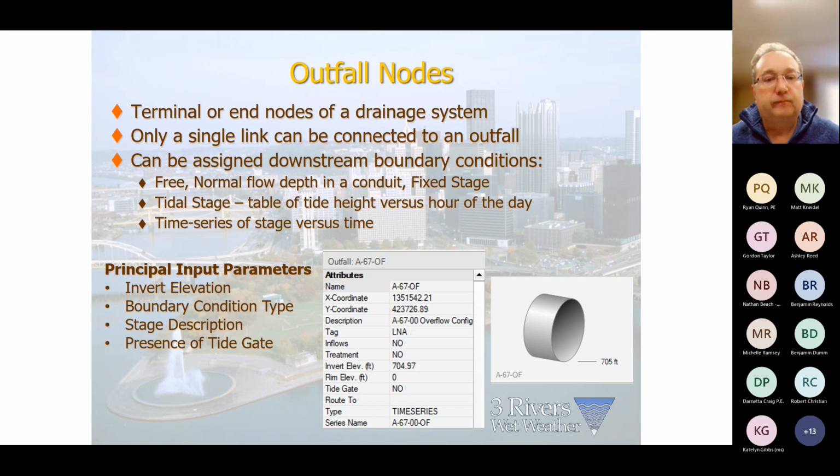is not a realistic approach. So, yeah. I think what Sam is saying, if you want to look at something like that, you should look at this box, the normal. Yeah, I've never played around with that parameter. So you're saying that could be another option, Sam, look at that, see what that is. So you're playing around with that time series. No, instead of using a time series, or if you don't want to use the time series, you put a different type of boundary in. And down here in the type, instead of picking time series, you could pick one of these other approaches and use a different boundary condition there.